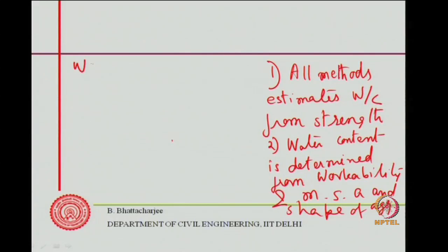So, water you determine from MSA, slump, and shape. Water cement ratio from strength.